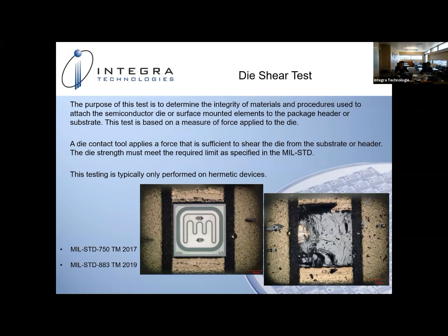All right, so die shear testing. Die attach integrity is tested during die shear testing. Force is applied to the edge of the die, the longest edge of the die, until the die breaks or separates from the area that is being inspected.